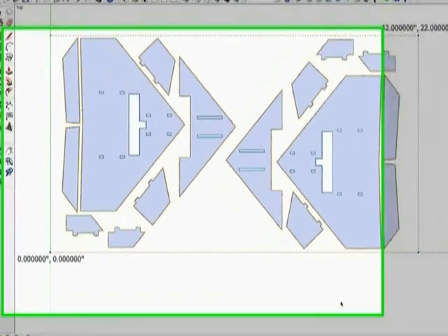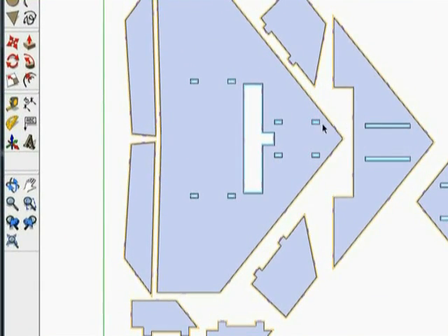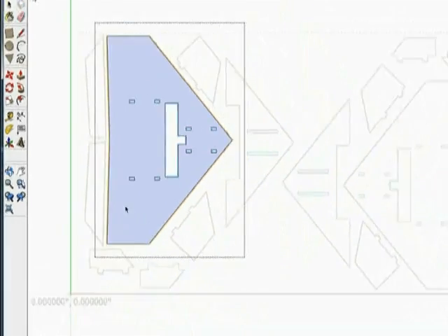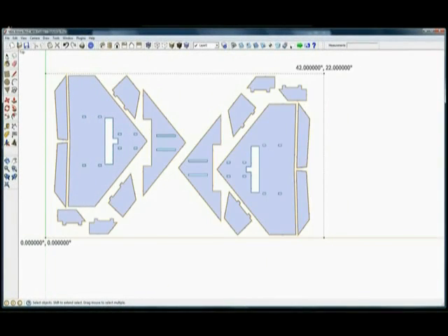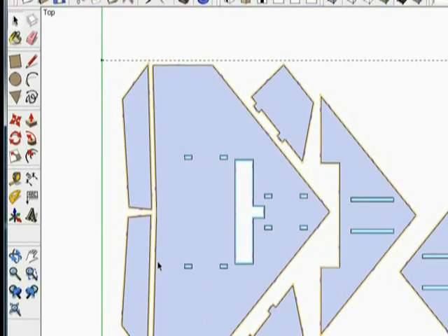Now here is an example where I've taken all of our work from this side, and I simply selected all of it. Oh, I've got that grouped. I didn't mean to do that. Well, the way I've done it is I triple clicked on everything. That allowed me to get the face, all of the lines, and then the third click allowed me to pick up the PhlatCode lines.